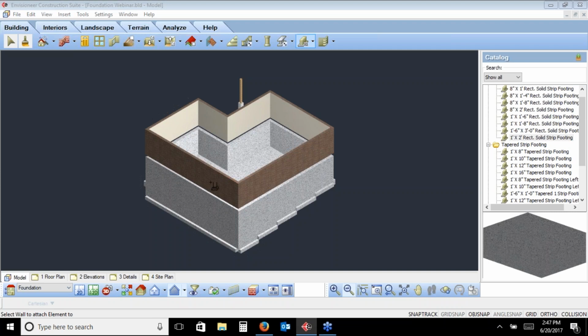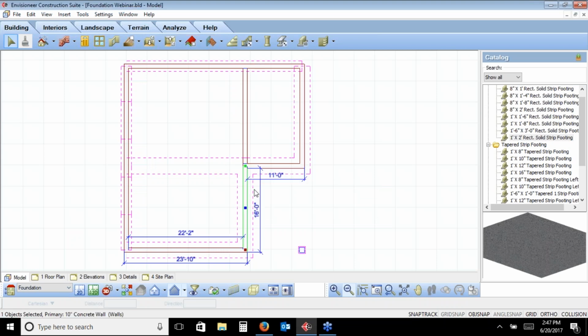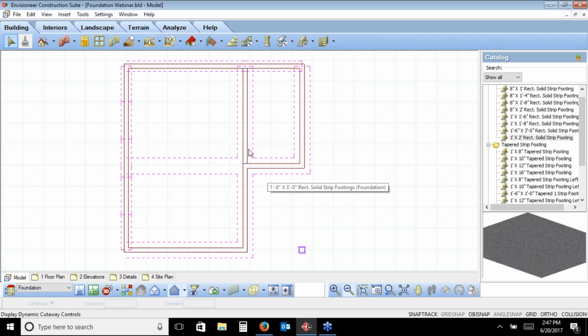I would still use the floor and foundation builder to track around the entire house. And then I would do the exact same thing that we did for that stepped foundation. So I'm going to just manipulate this here and draw out these foundation walls so that they're coming up here. I would show it that this wall here is at a different height and a different level.